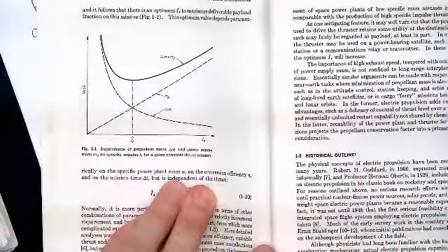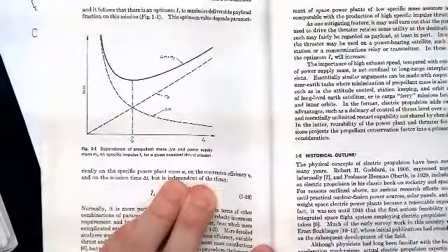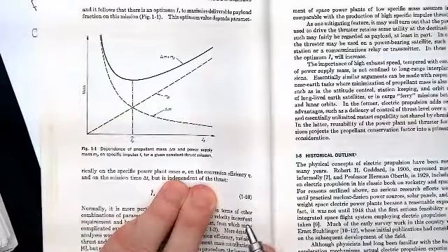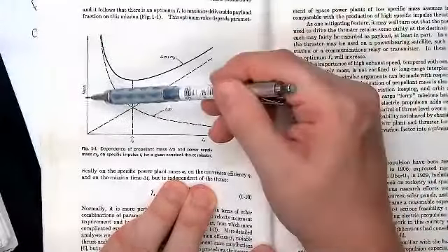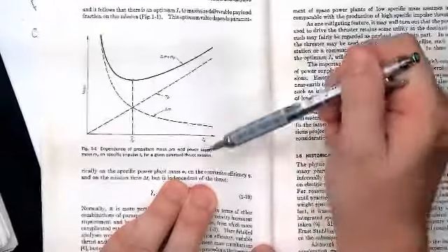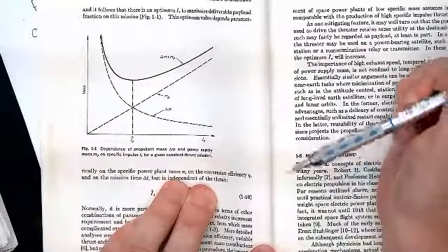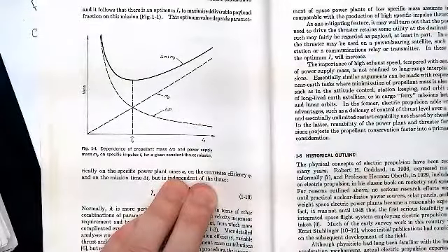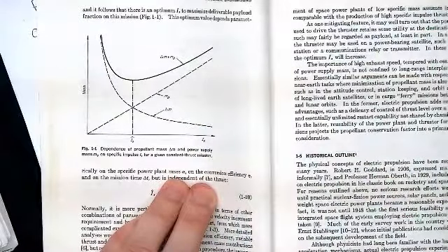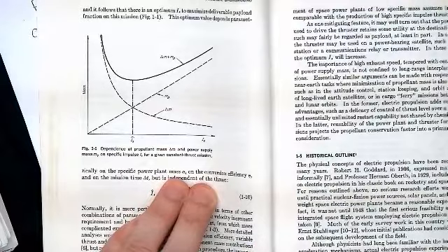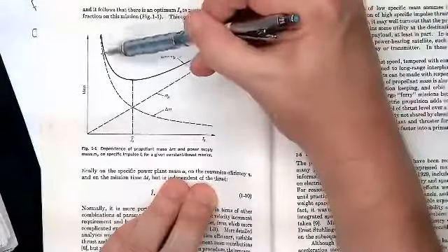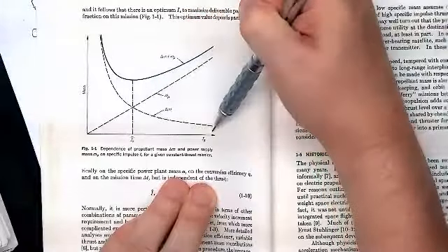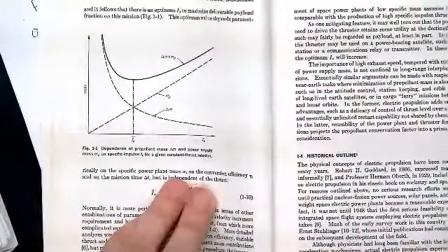So there is that figure. So we have mass of the system plotted as a function of ISP. So this delta M is the required propellant mass for a specific mission with some time delta T. And so as ISP goes up, mass drops.